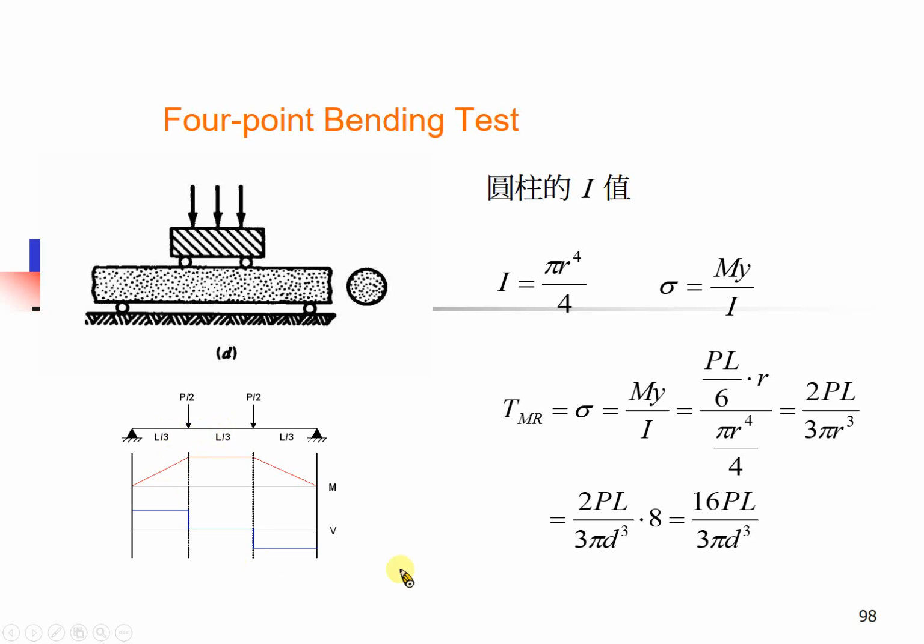And the other important thing, if you have a concentrated load at the center, then what is the distribution of the shear stress? There will be the maximum shear stress going all the way to the right-hand side to here and dropping down in the other direction. So almost nowhere is there zero shear stress. Everywhere has shear stress, except exactly the location where the load is applied.